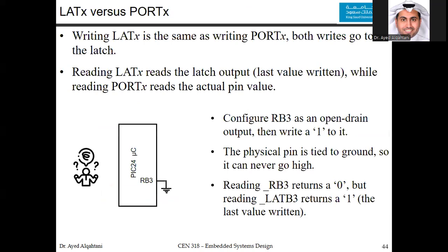Again, writing LATx is the same as writing PORTx, but reading is different. Reading LATx reads the last value that was written in the internal flip-flop, while reading the port reads the actual pin value.